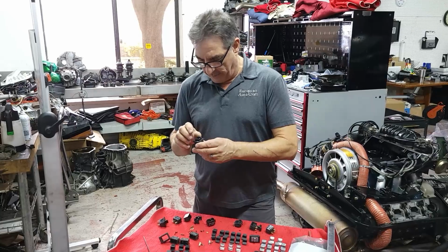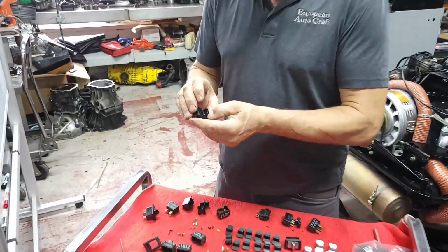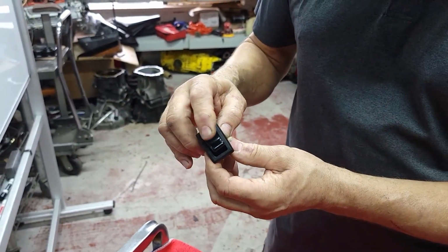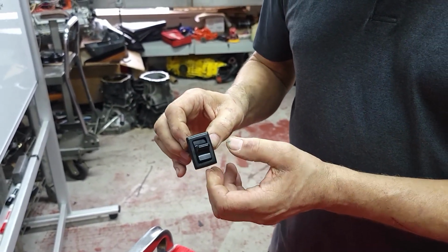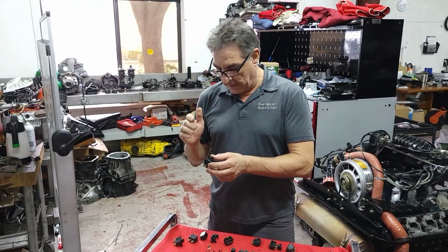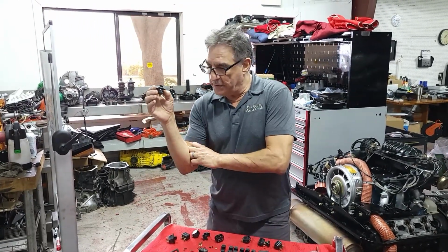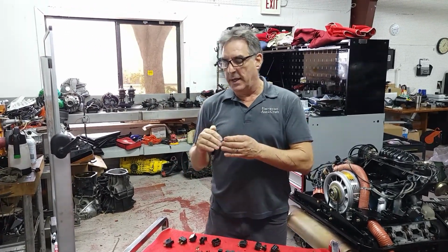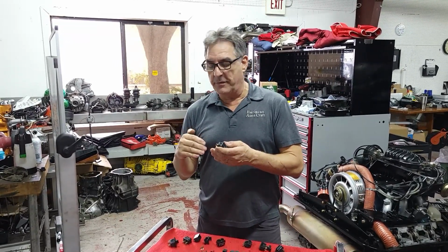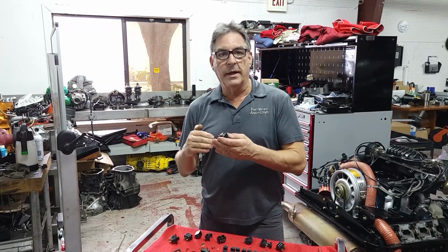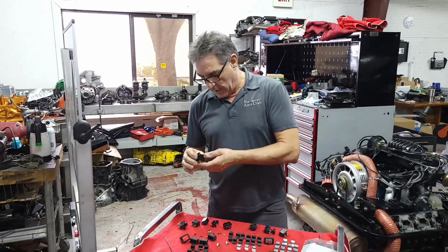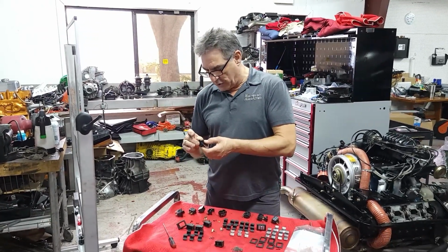So if you look, the shiny ones are the early window switches. You don't really see those anymore. But when they break, the little tab breaks off, and the window switch will stay in one state. What that does, it leaves the window on, either up or down, and it causes the motor circuit breaker internally to cycle. And it will cycle several times, in fact quite a few times, before it finally starts to get weak and the window will no longer have connection. It won't work anymore.